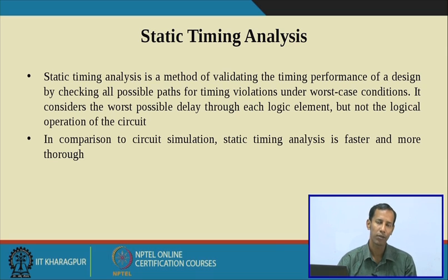Why do I need static timing analysis? For all worst case conditions, if there is any kind of violation. Whenever we are designing a complex chip, there might be millions of paths or millions of nets.